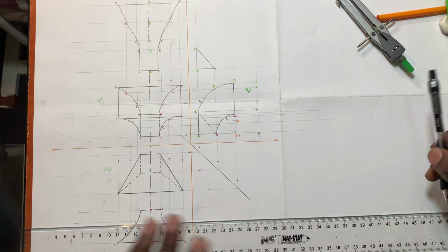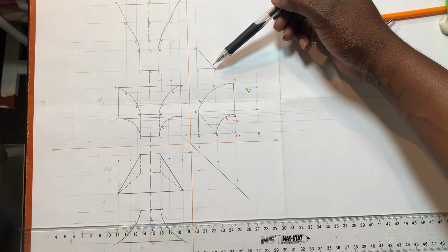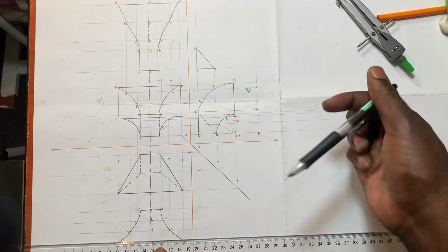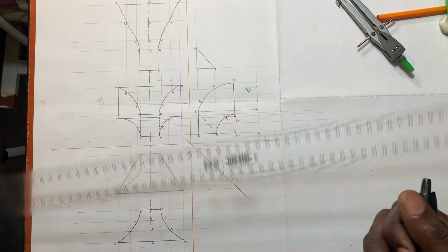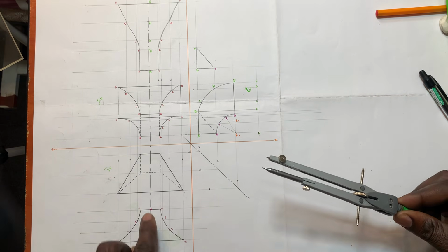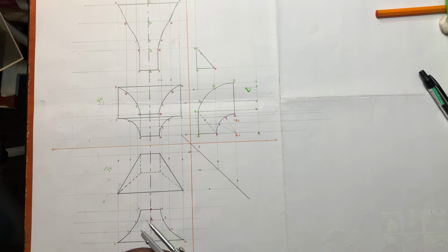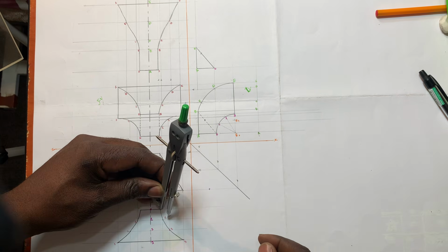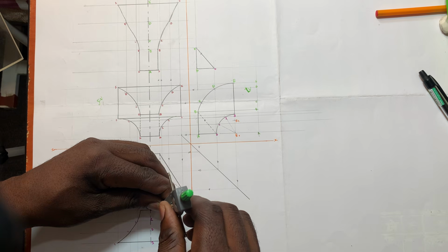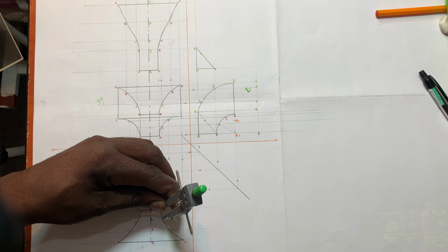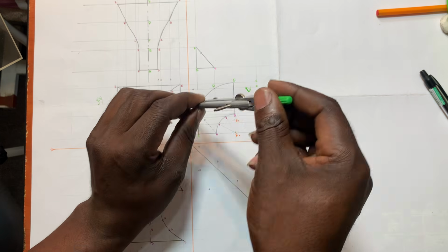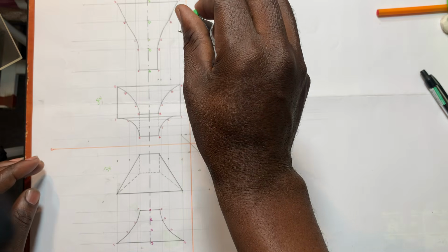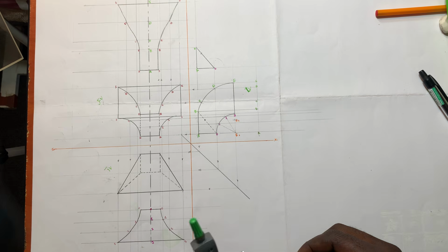Okay, so now what I'm gonna do, remember, where are we? We are here at our development. So we want to get the arc of 1, but we have to use the bottom part of it. However, there is a height concept there, so we'll rely on our development. You understand? So you can see when you place your drawing compass at A to 1 is different as compared to this one, which is this one that you have to rely on. So place it at A at 0 to 1, which is this one. So now come and place it here in my development. Then I strike an arc, faint, like this.